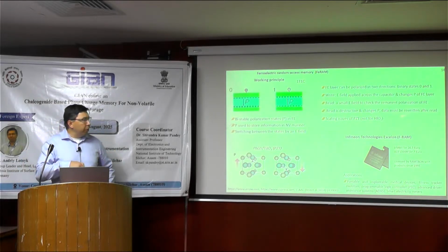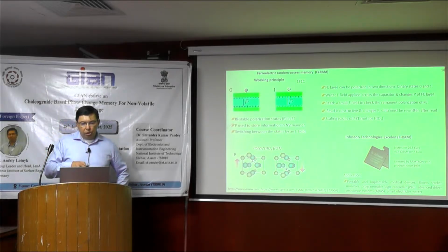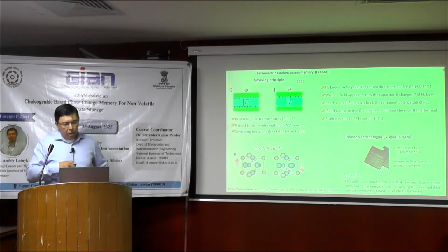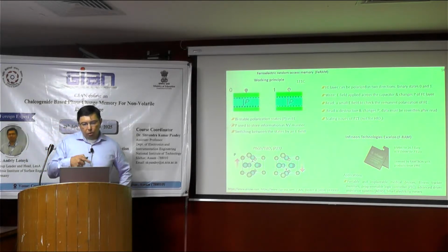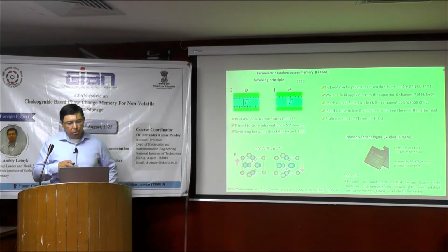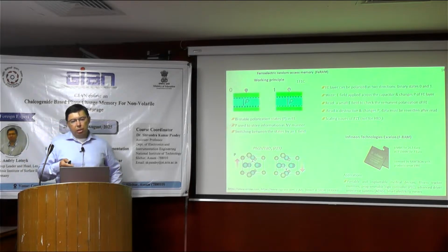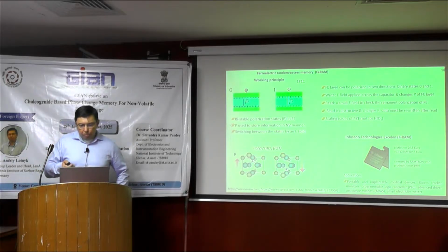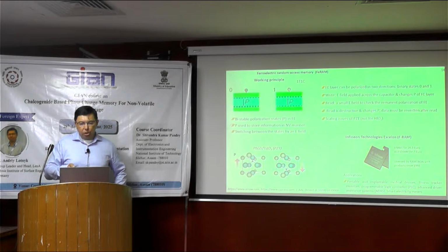But maybe hafnium oxide, a new ferroelectric material, can be used for this. Also, one requirement for such technologies is that you need epitaxial or highly textured thin films to achieve this high polarization, and it also requires thin film technologies and growth at elevated temperatures.